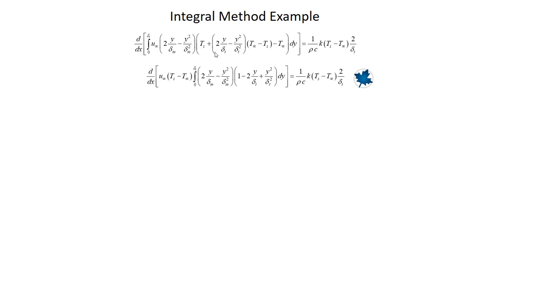And then also I have a Ts minus T infinity, right? So that actually appears multiplying this term. And T infinity and Ts, neither one of those two parameters can be a function of y either. So I can pull that out of this integration as well. So in front of this integration now I have u infinity and Ts minus T infinity, and now this is the integration that I actually need to do.